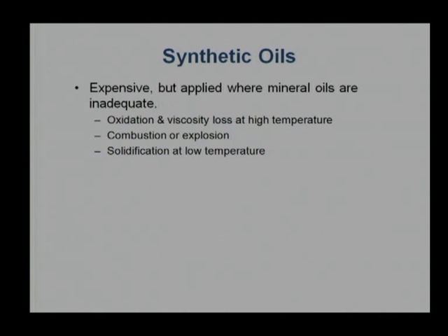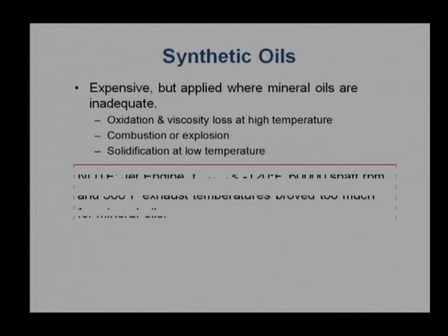And because of the cost, these oils should be used whenever mineral oils are inadequate: either they have more tendency of oxidation, more tendency of viscosity loss, more tendency of explosion, or more tendency of solidification. In those situations, synthetic oils should be utilized. Otherwise, mineral oils are very cost effective, and those oils should be utilized either in a pure form or with some sort of additives to give extra properties.